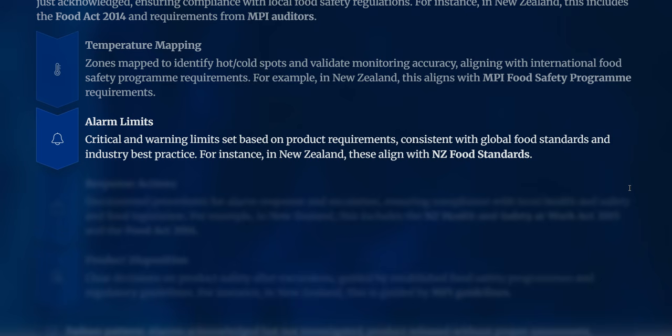If the temperature is climbing up, then you conduct trend analysis, investigate and apply corrective measures before it reaches minus 18. But if a breakdown happens, then you need to apply scenarios. So you need to build up scenarios in case of a breakdown of the coolers. What do you do? All right.